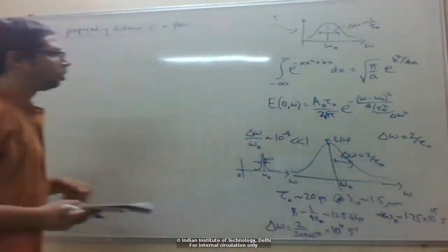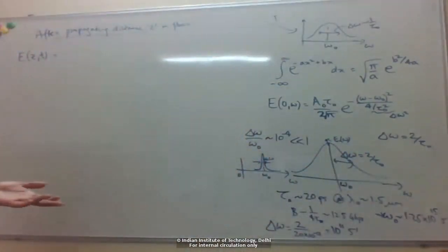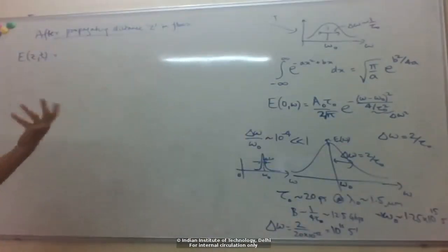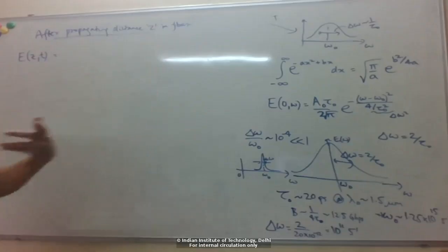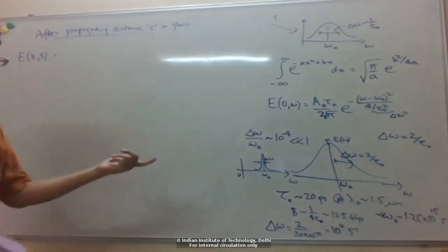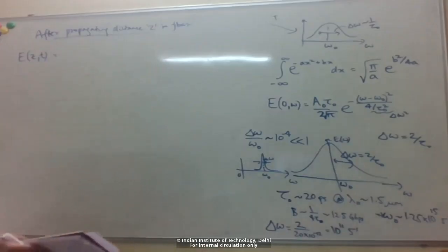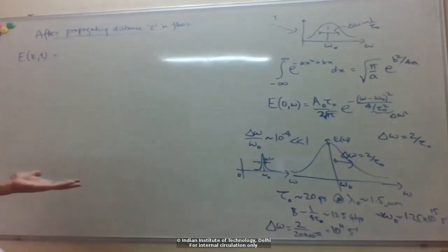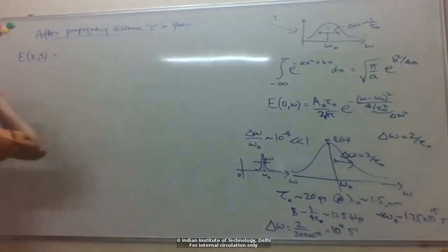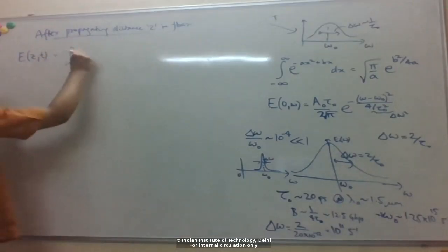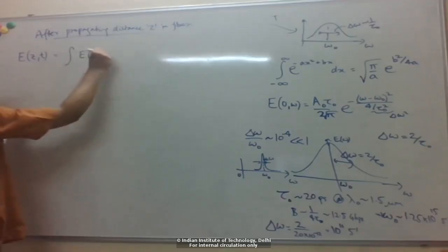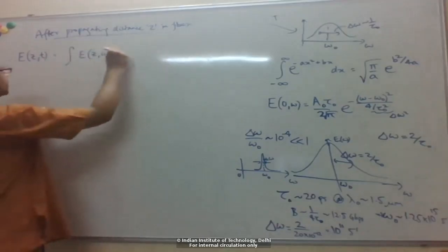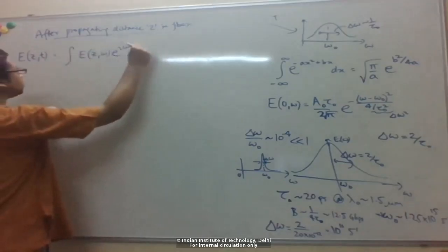And we know how monochromatic waves propagate through the fiber. It's just like the mode propagating. For a single frequency, we have some particular propagation constant beta, and it just acquires a phase e to the minus i beta z. So what we can do is easily find the spectrum at z, and then take again the inverse Fourier transform.